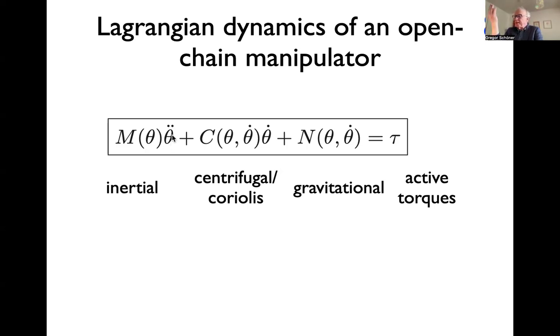So at the inertial level, it's very clear. If you accelerate your elbow, then the wrist will be in an accelerated frame, and that will make that there are forces acting on the wrist. You see that if you accelerate your elbow, your wrist would flap around from that. So there's some force transmitted from the torque at the elbow onto that. As a human, you would stiffen up and compensate for that. And in a robot, you have to deal with that. And the classical way is just to control it away, to discover that the interaction torques create some disturbance for other joints, and then you have a controller to make sure that that disturbance is counteracted.